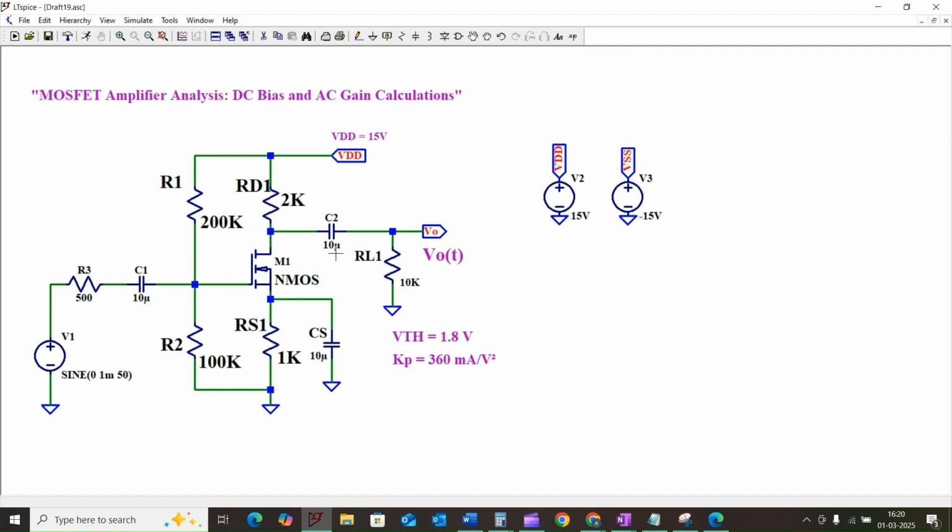It indicates an inverting amplifier with 180-degree phase shift, and the source resistance Rin reduces the gain slightly compared to the ideal voltage source. The gain is determined by the transconductance GM and the parallel combination of RD and RL, and the voltage divider effect at the input.